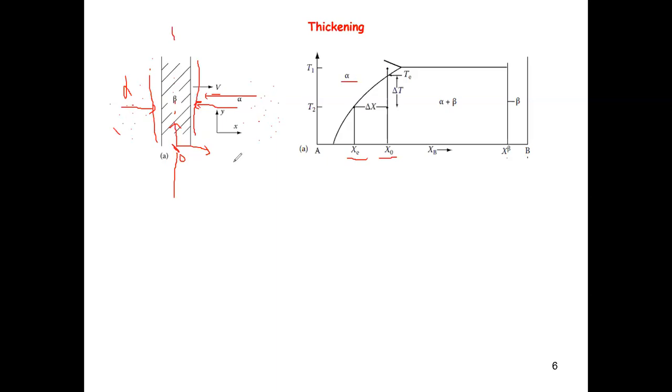And when these extra B atoms are moving away from the alpha phase, the consequence is that the alpha phase composition is going to get lower, and then approach the equilibrium value predicted by the phase diagram. So this tells you what's going on in terms of the kinetics of the system. Now, how is this going to help us in our analysis?